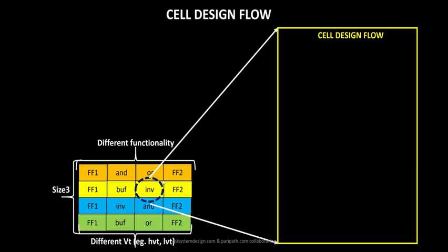The inverter has to be represented in the form of its shape, its timing behavior, its drive strength, its power characteristics, and so on. So this small inverter has to go through a typical cell design flow, and I'll very soon fill up this table. The point is that a cell as small as an inverter has to go through typical steps of a cell design flow, and that's huge. You will be amazed to see what these steps are. So let's look into those steps.